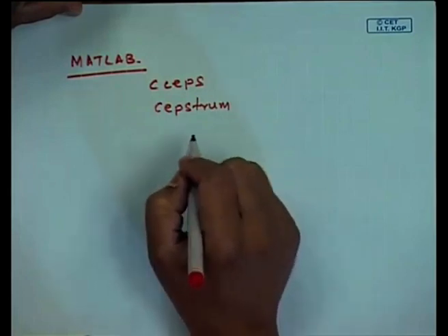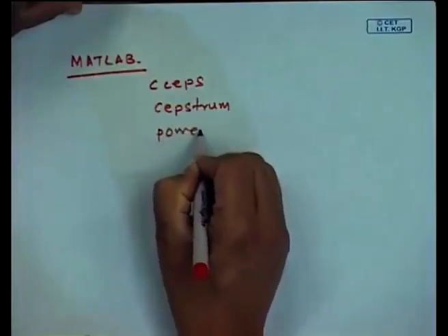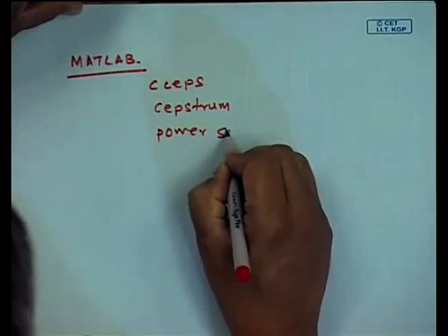If you do not take the logarithm of the amplitude, you may also land up with different forms of the Cepstrum, whether it is a complex Cepstrum or a magnitude Cepstrum. So, there are many ways by which people represent the data out of a Cepstrum. And sometimes they call it a power spectrum. If you are dealing with a power signal and auto power spectrum, then you will have a power Cepstrum.